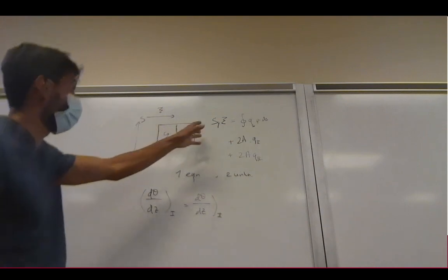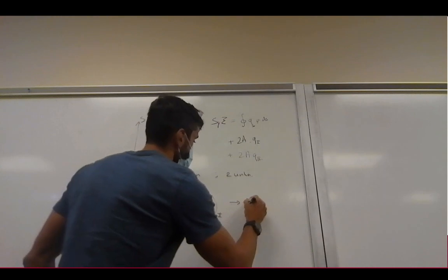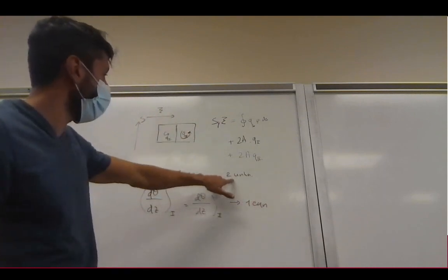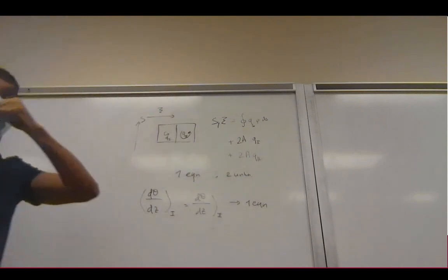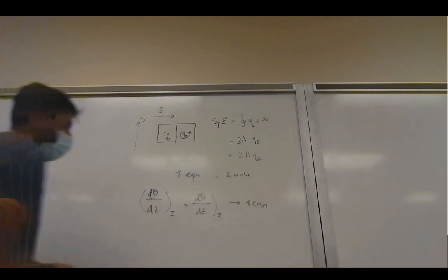If there are 3 cells, we equate cell 2 to 3 as well, and this gives us an additional equation. Then we have 2 equations and 2 unknowns, and we can solve for both q1 and q2, and then add them to our open shear flows and solve the problem.